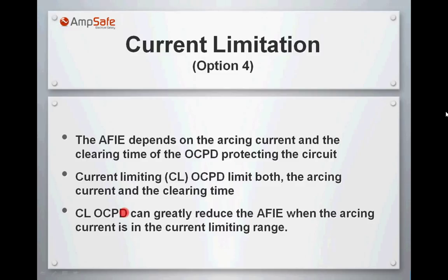So if the arcing current is above that current limiting threshold, yes, you're going to see a substantial difference in the ArcFlash incident energy, and I mean substantial, not little, between a non-current limiting device and a current limiting device for the same amount of arcing current. Okay, so my recommendation is, yes, definitely consider the current limitation of current limiting devices.